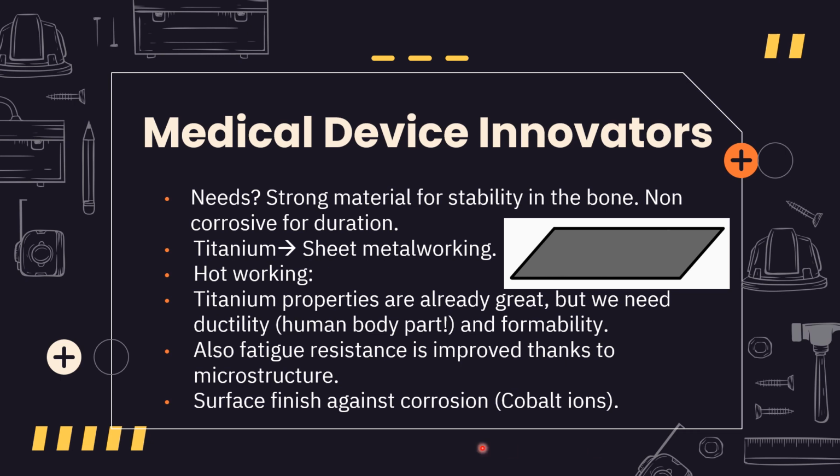Finally, as I said, to improve corrosion resistance, I would introduce a surface finish, which can be, for instance, some anodizing with cobalt, in order, as I said, to reduce this corrosion.